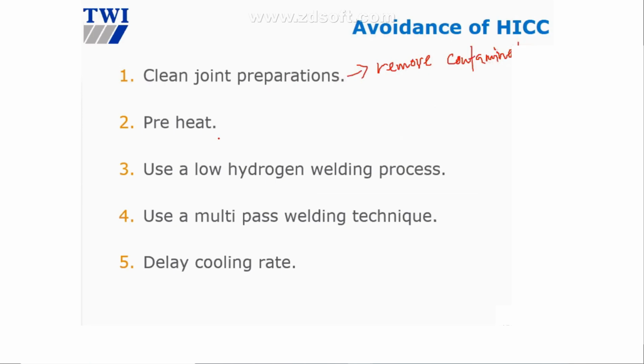We do preheat to slow down the cooling rate. That's the purpose of preheat, to slow down the cooling rate. Use low hydrogen,